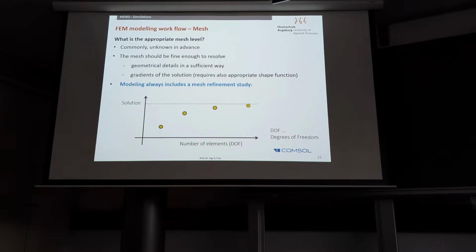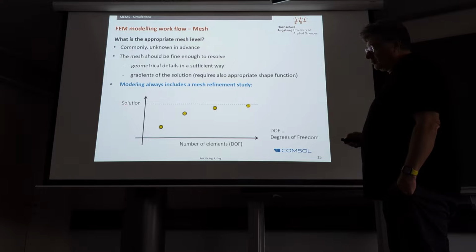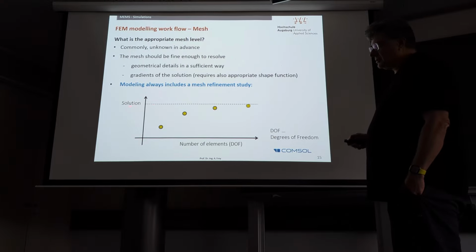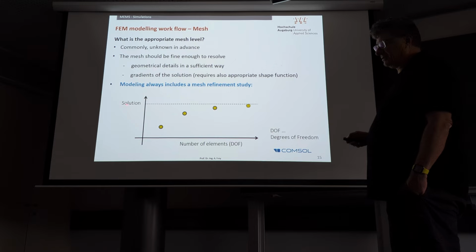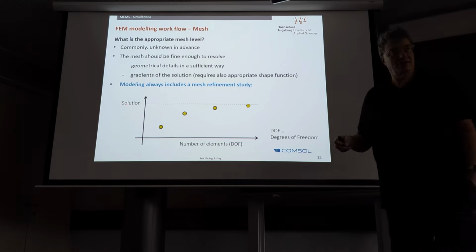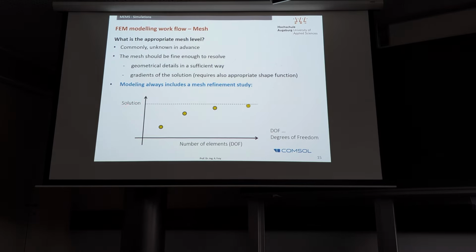If you make a finer mesh, you get more temperatures calculated in more grid points. So you start with a kind of low number, then you should look at the solution. This seems so simple, you can put that name solution on that axis, but in real life, what does it mean, look at the solution, to get a diagram like this?